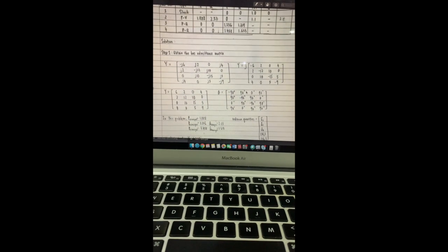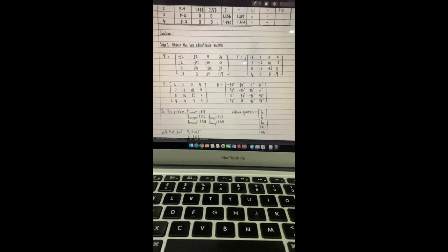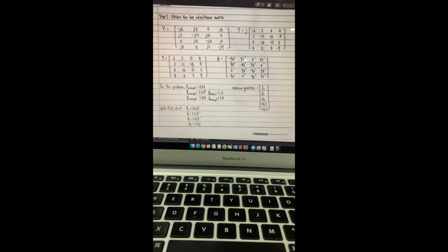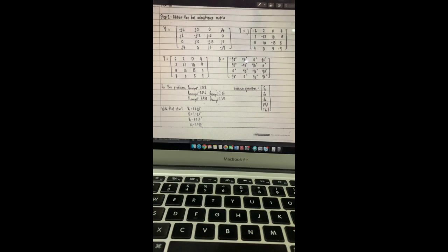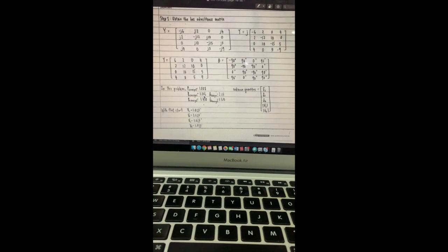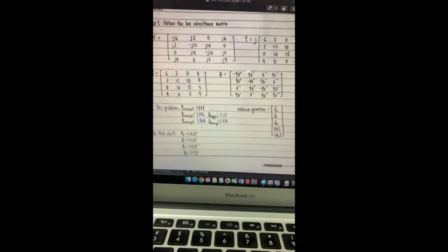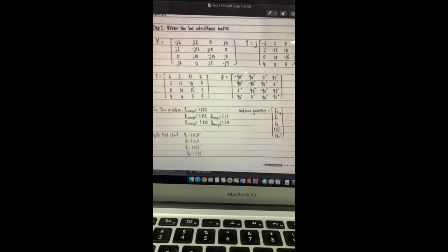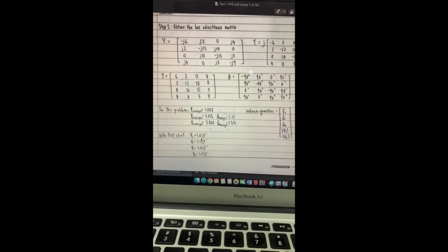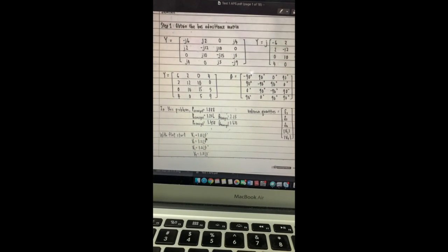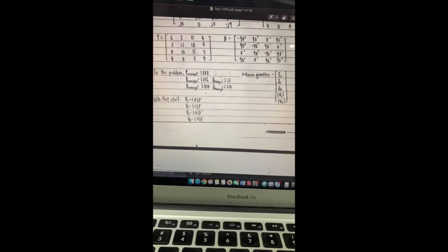Firstly we will obtain the bus admittance matrix, where we invert all the numbers here to get the Y. Then the P2, P3 and P4 we will also assign first, and also the Q3. The unknown quantities are stated here, the delta and the V3. With flat start, we set all equal to 1 volt and V2 is 1.1.